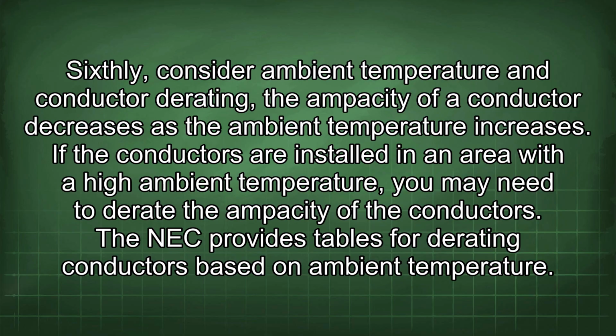Sixthly, consider ambient temperature and conductor derating. The ampacity of a conductor decreases as the ambient temperature increases. If the conductors are installed in an area with a high ambient temperature, you may need to derate the ampacity of the conductors. The NEC provides tables for derating conductors based on ambient temperature.